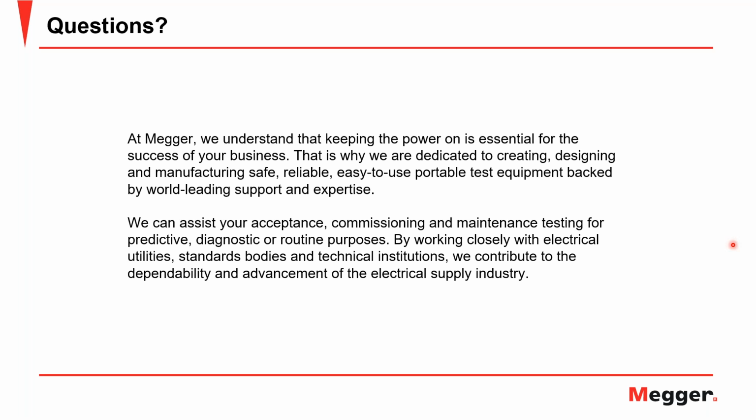I guess it would only make sense to me if you have some sort of capacitive compensation in lines. But again, in that case, you have to do a proper short circuit study and configure your line. But it's not something that I can advise one way or the other without knowing the exact characteristics of the system that you are trying to protect.